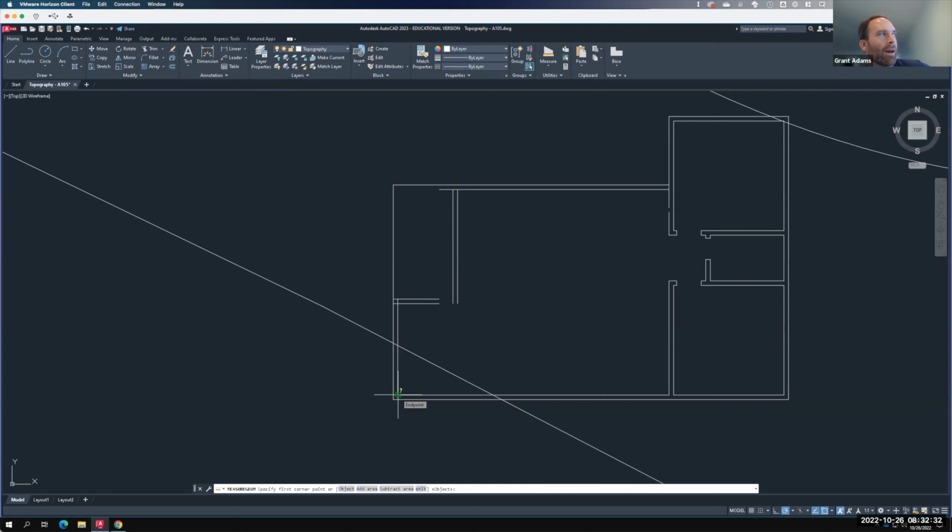I know, for example, up in Tahoe, they've actually separated out building square footage and deck square footage. Building square footage has to do with the footprint. So all the way around the outside, even if you can't step on it, it counts. But their decks have a formula that calculates square footage based on how high they are off the ground. So if it's taller off the ground, you can have a bigger deck and it counts as less square foot. So it's really baffling, but that's the way that jurisdictions work.